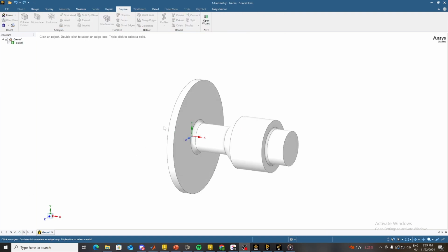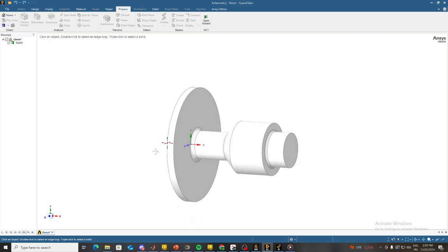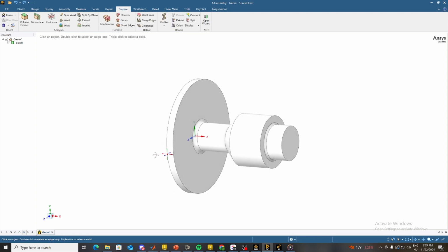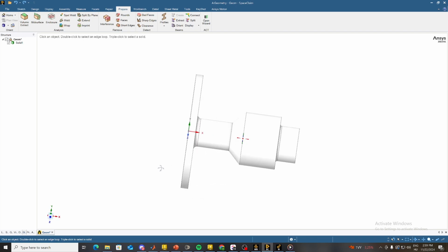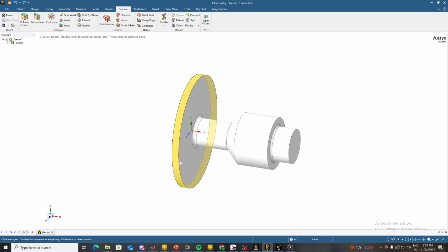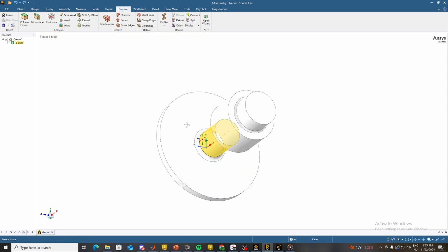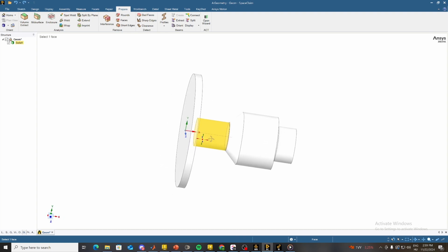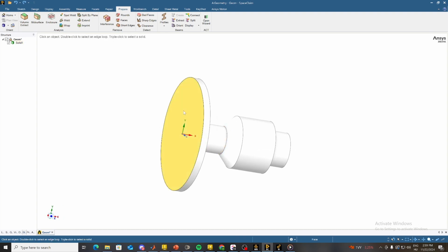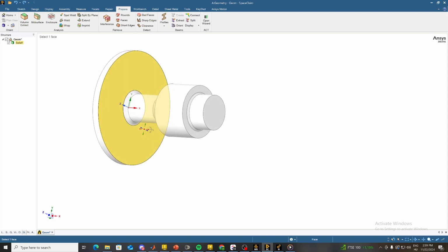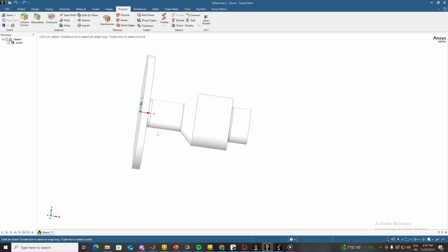So one very important thing: while in CFD calculations the x-axis is the one that should be used as the axisymmetry, here in the mechanical, the program will only understand the axisymmetry if it will be on the y-axis. So we need to define our problem so it would be axisymmetric on the y-axis.